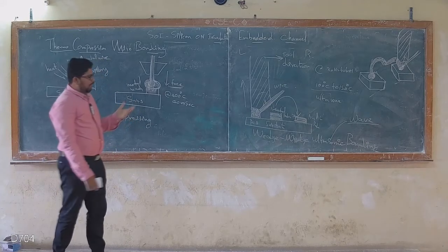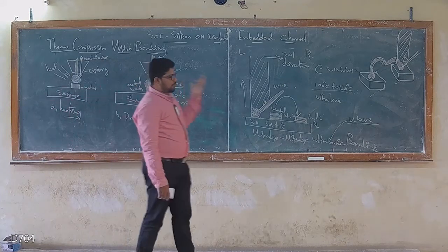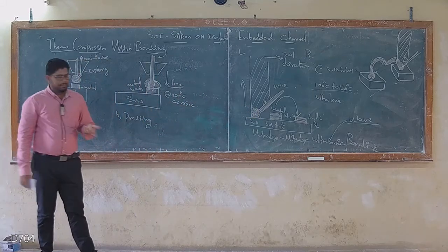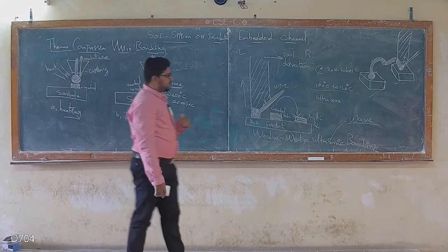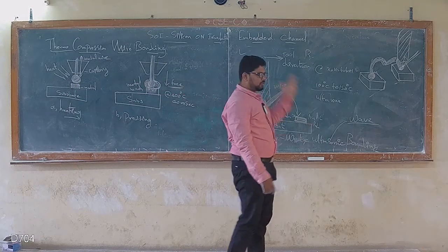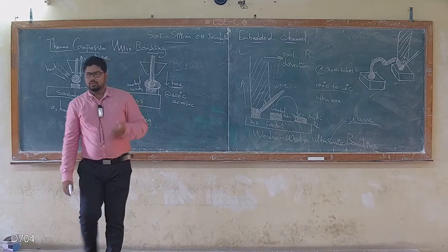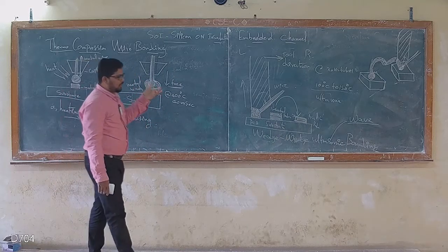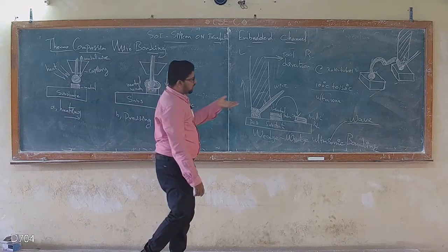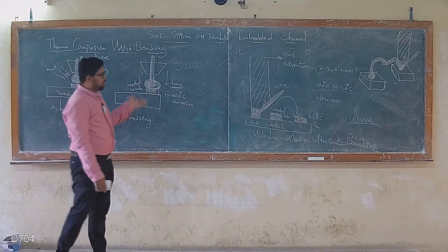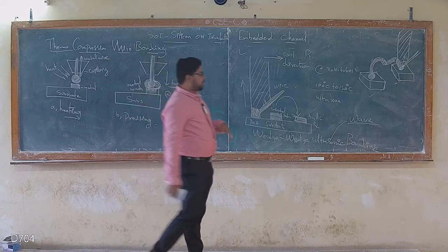After making an effective bonding between palladium and indium, we could easily remove it with the help of a laser. There are two systems: one is the donor substrate, the other is the acceptor substrate. The donor substrate will have some metal on it, called palladium. The acceptor has its own metal called indium. So that can happen in low temperature surface bonding.